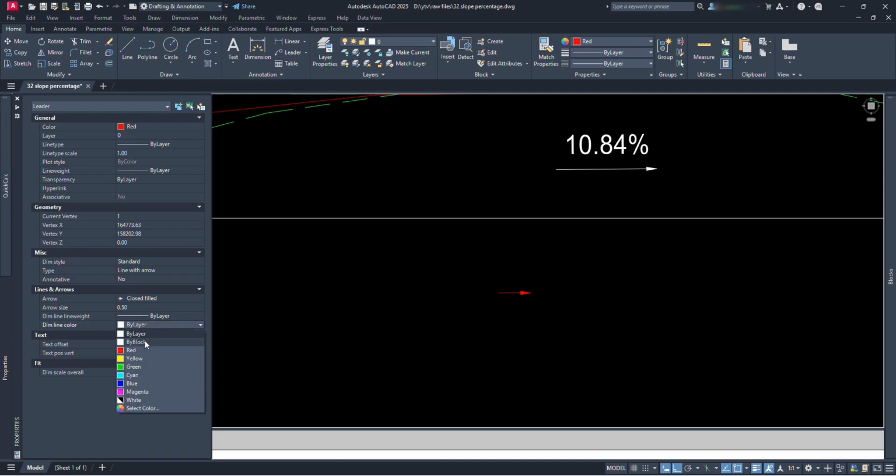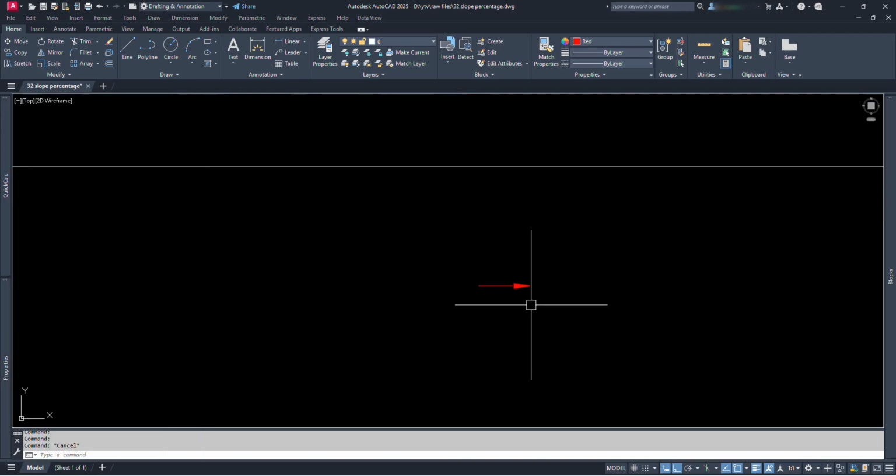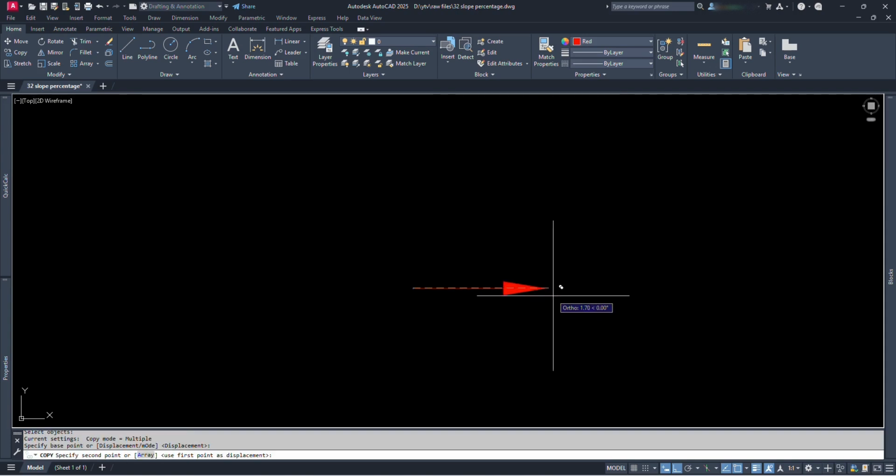Then, let's put 2 points, one at each end. Let's type POINT and press enter. Click at this rear end. Copy this point to the front of this arrowhead. Click on the arrow and this point at the same time. Move this point to the arrowhead end. Now it looks like we only have an arrow. Let's change its color to red.